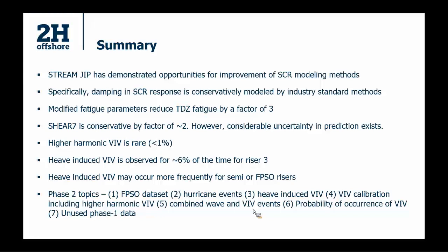Okay, great. Next question was, which values of damping have you used for the SCRs? We used the 0.3% structural damping. We used it just on the stiffness matrix only. So we are being quite conservative, actually, even when using it.